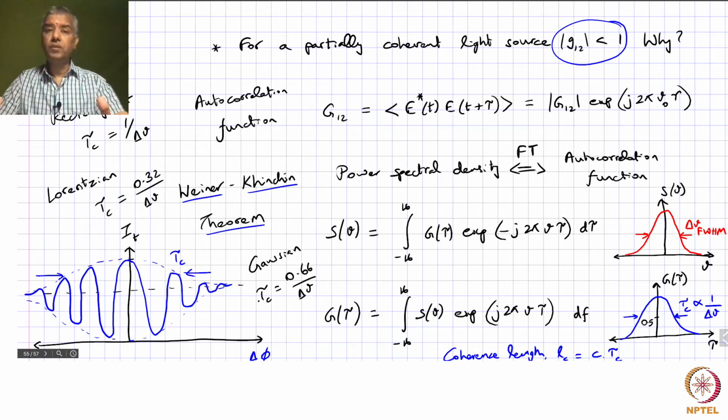So you certainly need a highly coherent laser so that the path length difference, even if it is on the order of a meter over kilometers, you can still tolerate that. That essentially tells you that you need to use a laser whose line width is on the order of kilohertz, even less if it can be allowed, right? So that is one extreme of an application where you need highly coherent light.